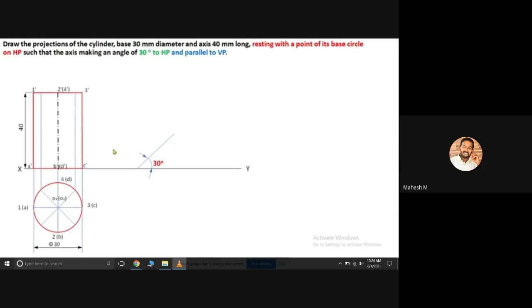Opposite scale will be in the position of 90 degree. Okay, so please use your drafter scale for creating this third diagram. If you're doing that, please align any one scale on this inclined line, then the opposite scale will be with an angle of 90 degree. Okay, so please move your scale exactly to this position. At any point, you'll be having a 15 mm distance between these two surfaces.